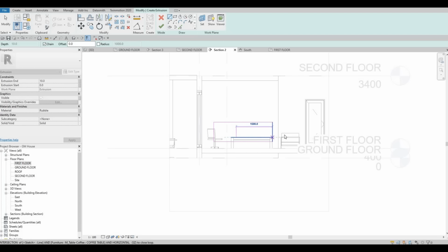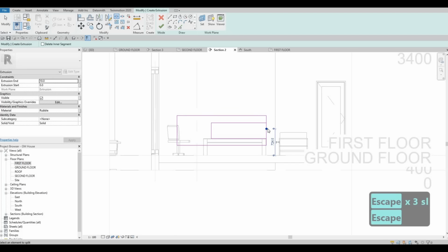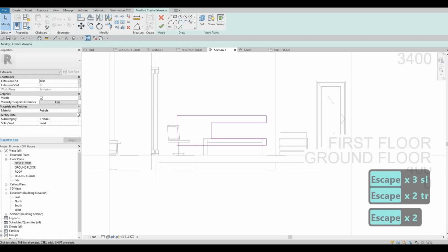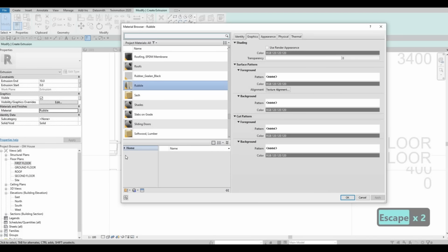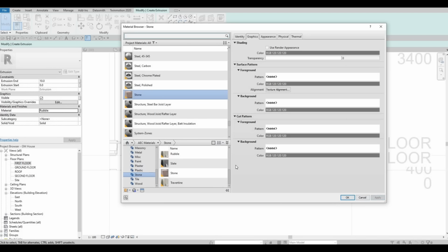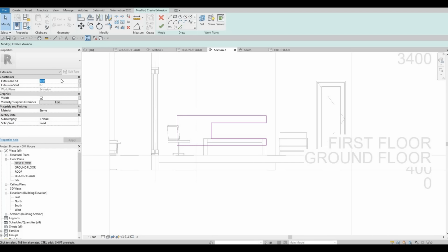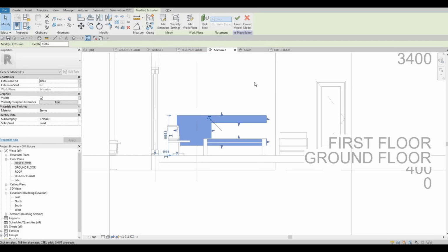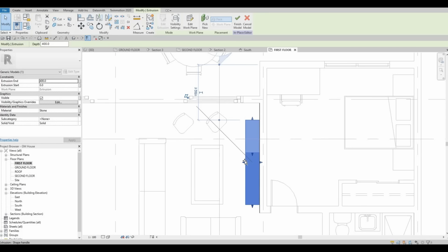So on something like an electric heater here. There we go. Change this again to a different stone. We can use this. This one should be around 400. Click on finish. You could see it in our first floor. I think that's good enough. Let's put it at 350.